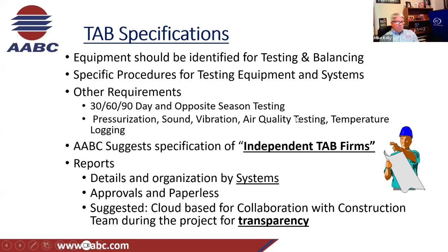Air quality testing, not too much of that is spelled out in specifications, but we have seen it coming up recently within the past 3 or 4 years. And we all know why that is. And then temperature logging, where, when, and how. If you're doing temperature logging at 1 a.m., probably not too helpful to anybody on the job, but it might be the best way to do it because no one's around and doors aren't being opened and there's less disturbance, and you know that temperature logging is pretty steady in those hours. Well, that may not help you because we really want to know what happens during the day when people are there doing business or utilizing the facility. AABC suggests specification of an independent TAB firm.